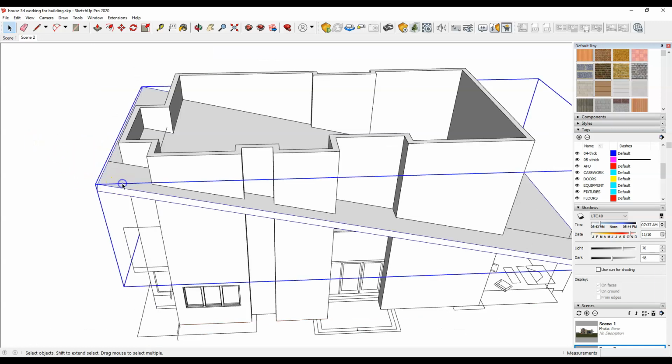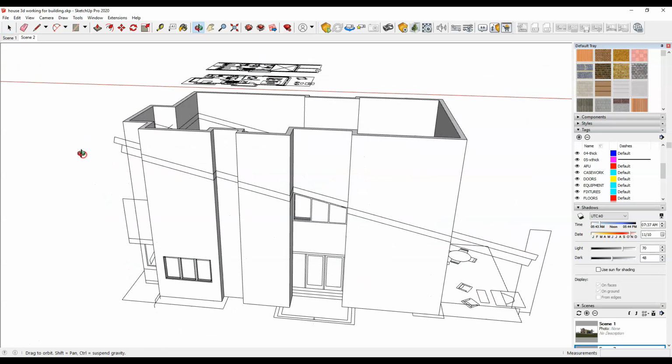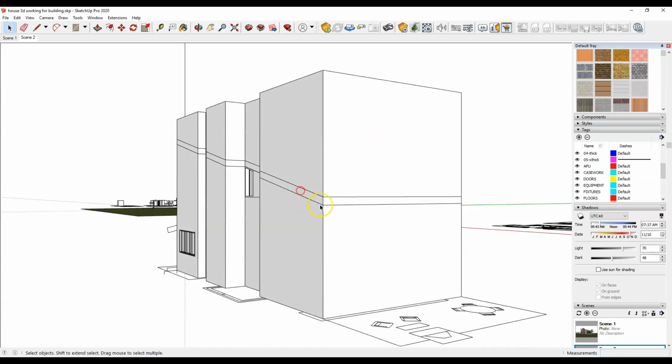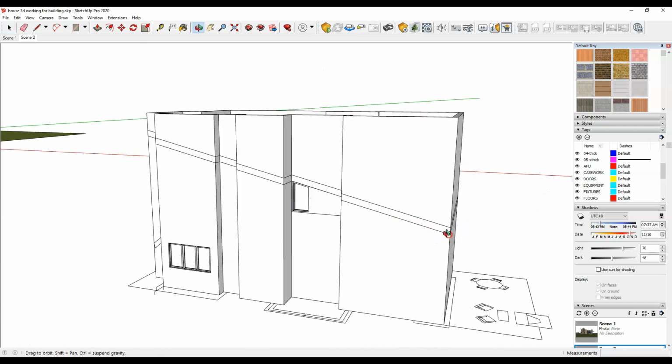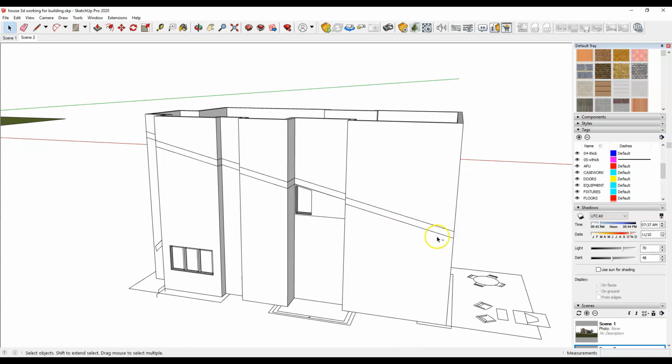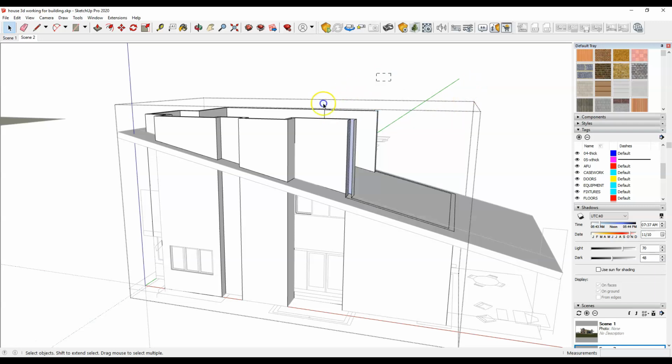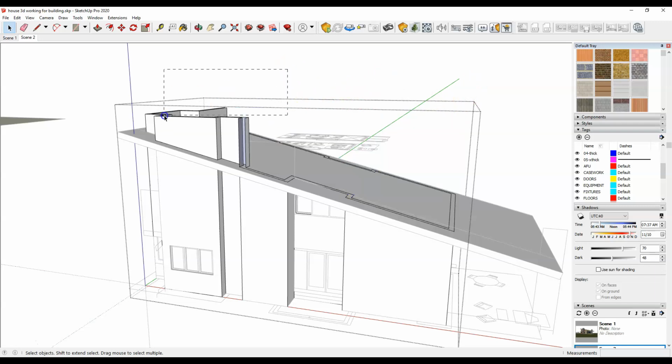And if I were to quickly demonstrate this, if I were to delete my roof, you can see what has happened. And actually, let me delete the CAD as well. You can see it's cut the roof right onto that surface. And all I need to do is undelete those things. All I need to do is come into the walls and delete those top parts of the wall away. They'll cut right at that surface there, right?